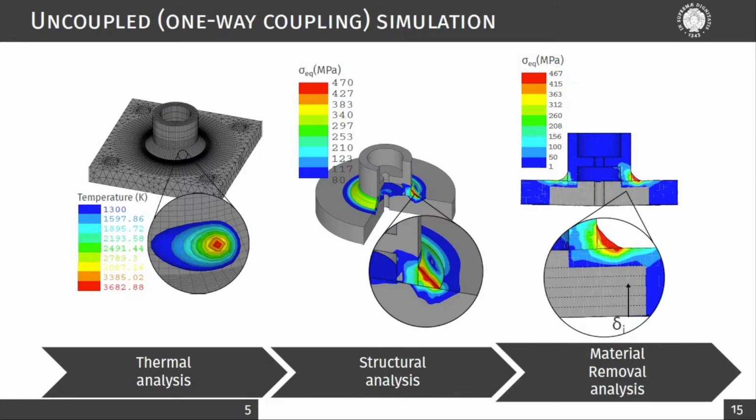The following session deals with the numerical simulation and the assumptions underlying it. To simulate a welding process, a thermal structural simulation was made. An uncoupled formulation was used to describe the welding process, as the displacement obtained during welding are limited and have negligible influence on the thermal distribution. This kind of formulation is so acceptable in this context.